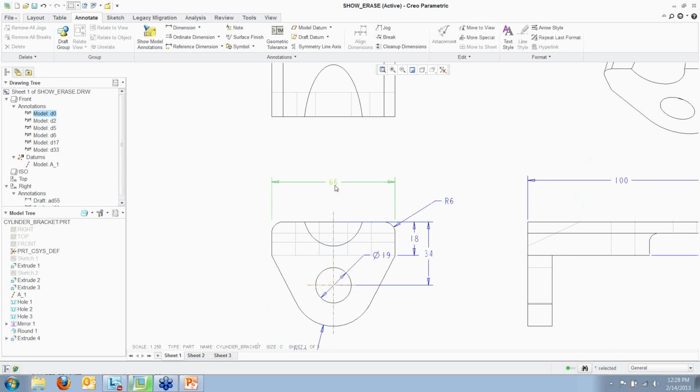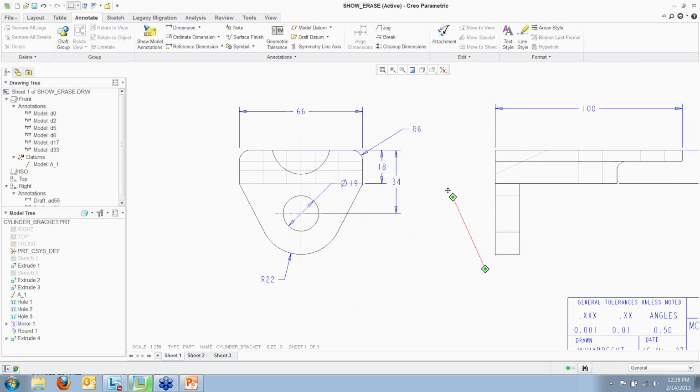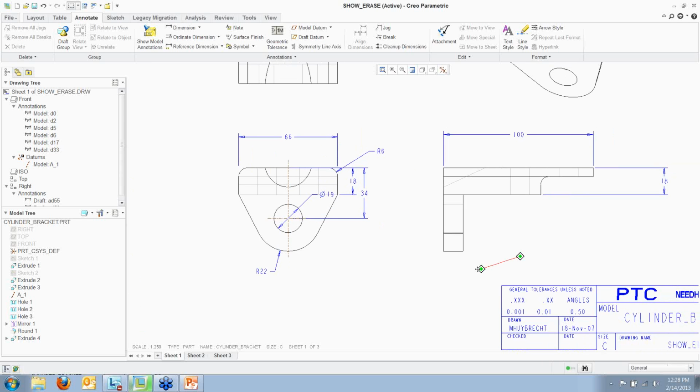Also, when I'm moving dimensions around and dragging them up and down, I've got a lot of the same drag handle type features as before, but you'll notice that the drag handle that was on the top for skewing my dimension is no longer there, which I usually do a pull, and most people don't use that. But if you do use it, if I right-click and pick Skew Dimension, now I have the ability to skew my dimension. Like I said, most people don't use that functionality, but it has frustrated a couple of my users.